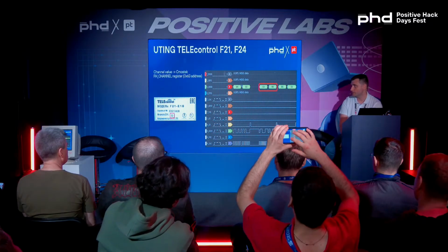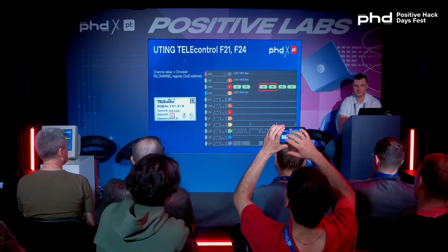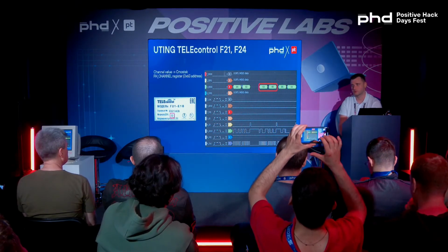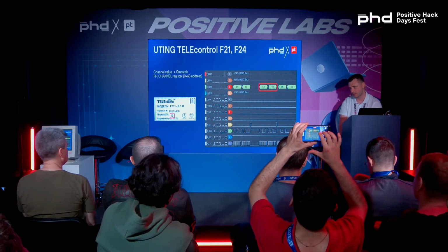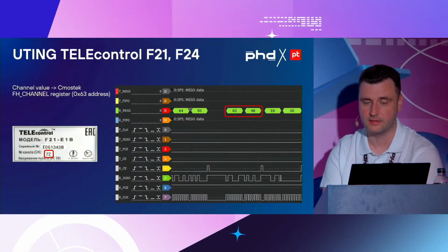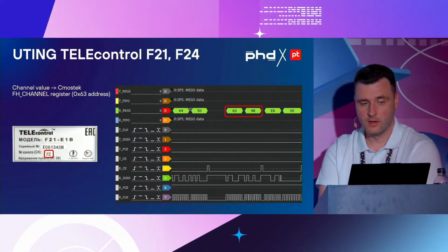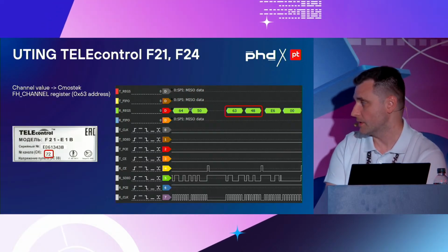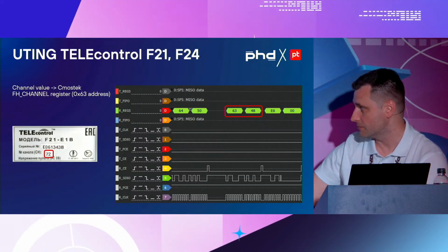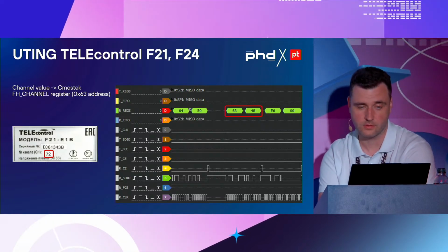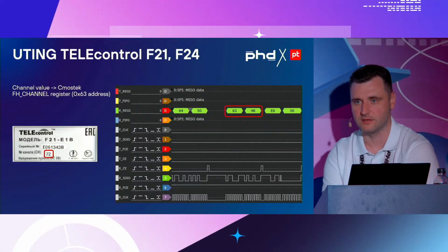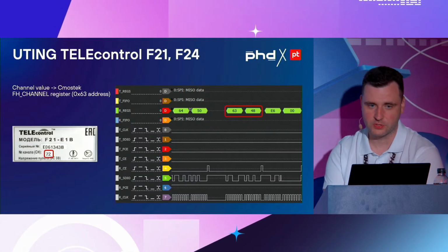We sniffed several devices, and we realized that the initialization of the connection between the receiver, the transmitter and the chip sets a lot of parameters, preamble and others. They are the same for all the devices. The only thing that differs is the channel number. On the label you see the channel number 72, so it would be written in the chip's register called channel.